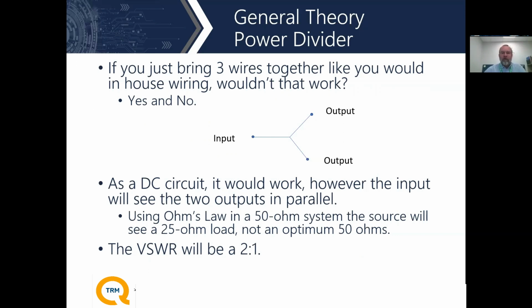Virtually all of our networks rely on a 50 ohm system. And this is important because as we're going through the system, we have to make sure that we have maximum power transfer throughout the entire network, and we don't have energy bouncing around where we don't want it.